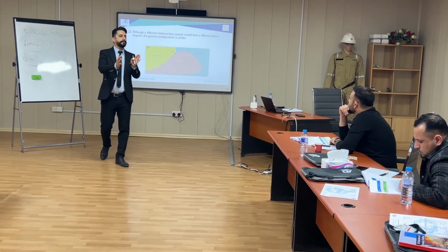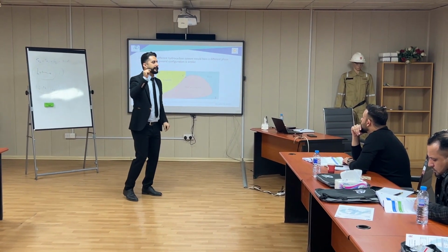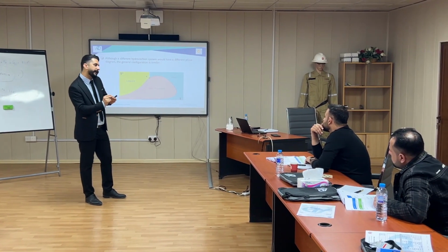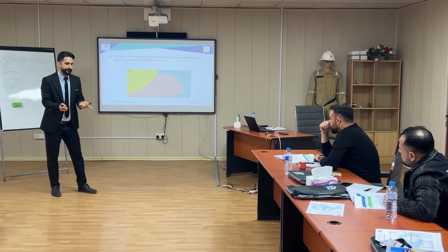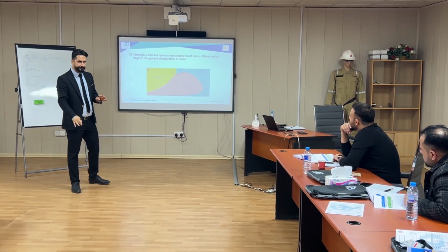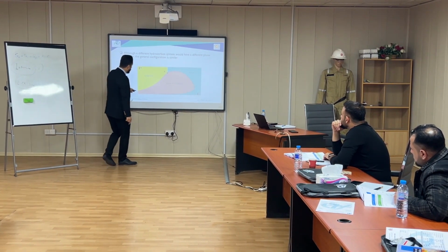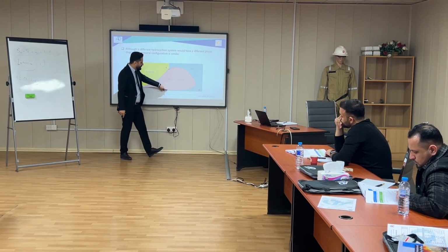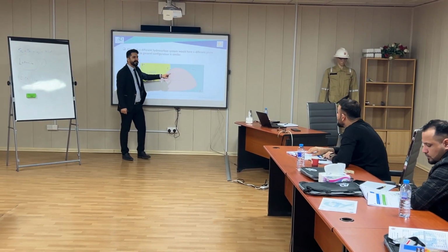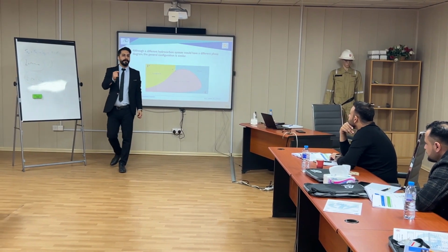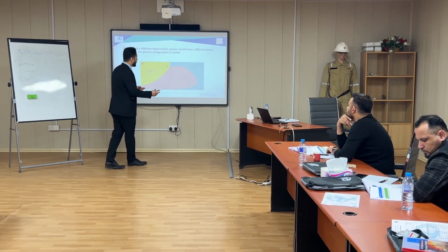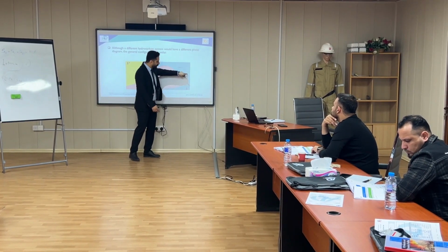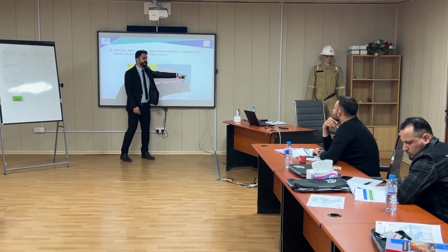Before that, we are going to have just liquid, and at this point, we are going to see the first bubble of the gas. So we are entering a two-phase region. Got it? Yes. So this is called the bubble point line. This line is important for us too, and this is called dew point line. Dew point. Yeah. And suppose a situation that you are going to have constant pressure and you are going to decrease the temperature of the gas.